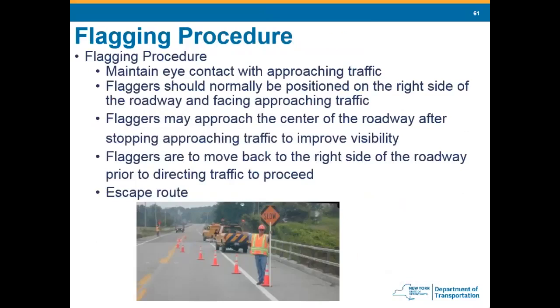Position on the right side of the road. Here it does say they may approach the center after traffic has stopped, which is good. You walk out to the center, you see what's going on, you check with your other end of the work, see if we can let people go yet. And they are to move right back to the side of the road once they've directed traffic to proceed. And they need to have an escape route. If somebody comes wheeling through here that's not paying attention, they need a place to go. Over that bridge rail or somewhere. What's on the other side of that? But they need to have a place to go.